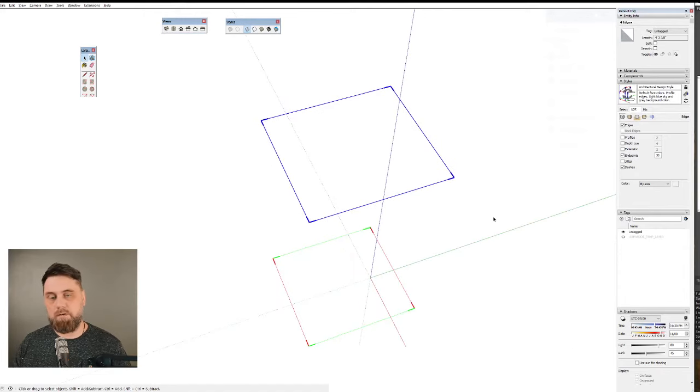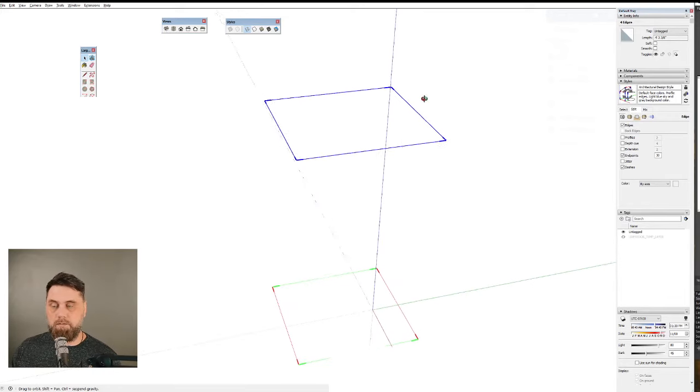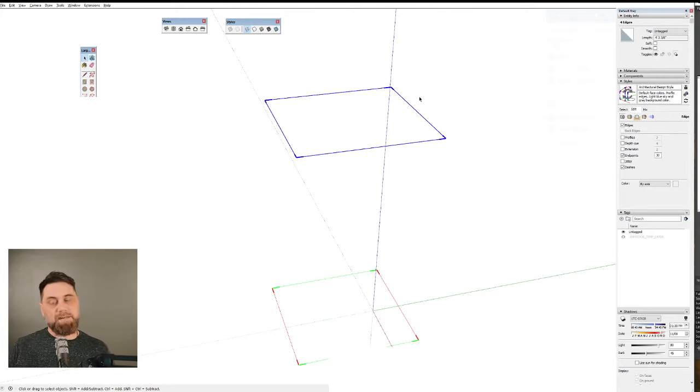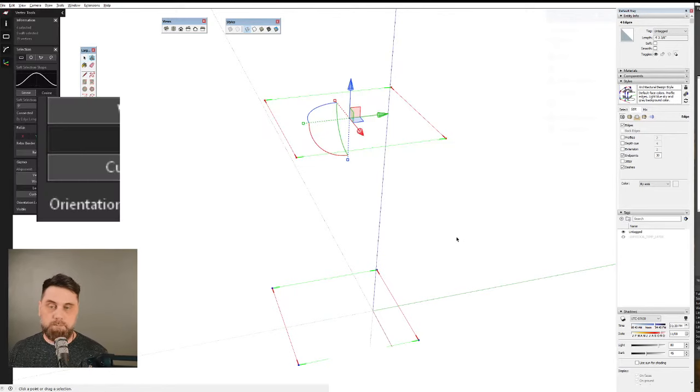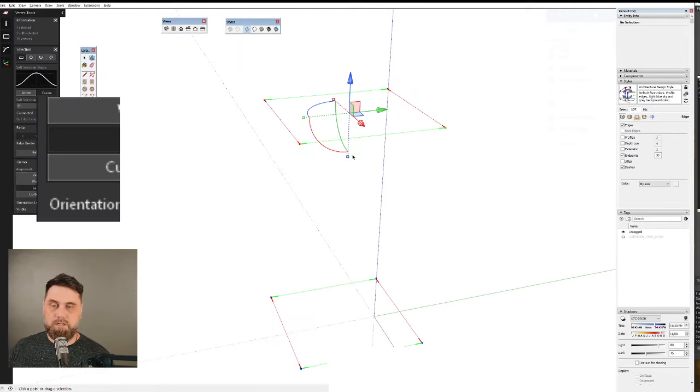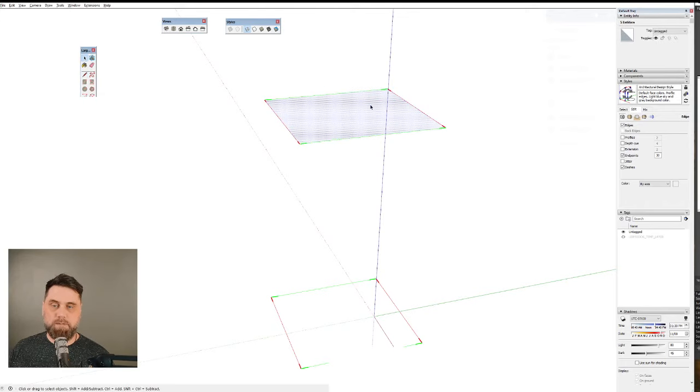All right, so that's going to happen to you from time to time. The best thing that you can do, there are ways to remedy this. There are plugins that will flatten. Vertex Tools, the plugin I just showed you, allows you to come in and scale everything on the blue direction to make sure everything's completely flat. So if I would just scale that up on the blue, that would generally flatten things out. And now we would get a face showing up. Okay, so there's free plugins that'll do the same thing, flatten and stuff, but we'll talk about that.